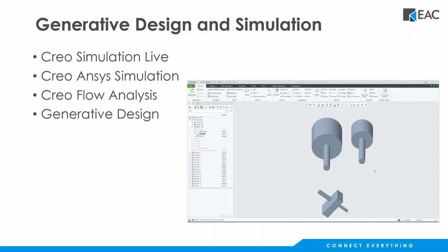And then finally, we have updates for generative design, and this is also what I'll be showing today during the demonstration. We now have an ability to add a safety factor target to minimize mass to that safety factor. We have updates in the modal optimization, where we're able to maximize fundamental frequency at mass and volume targets, or minimize mass at fundamental frequency floors.